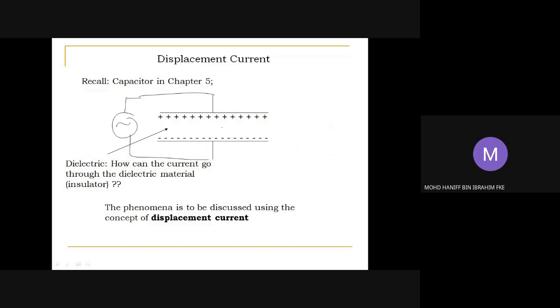So that should be the supplied voltage to this capacitor. There should be a current flowing in these conductors, and since they are conductors, the current flowing should be the conduction current. Conduction current originates from the conduction current density, JC, which equals sigma times the electric field.